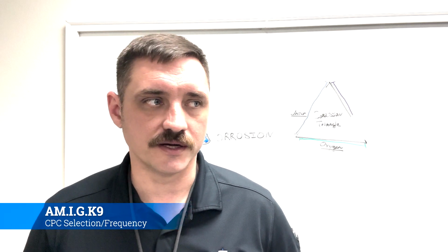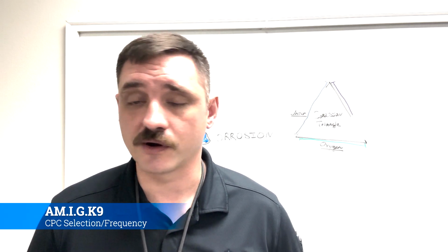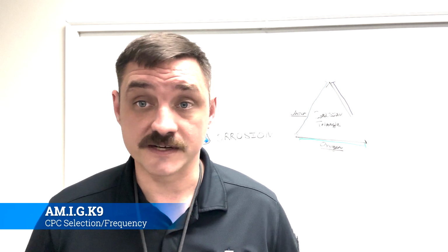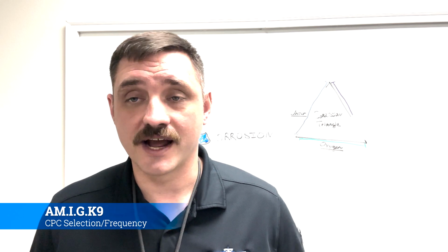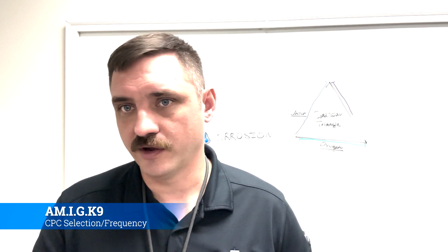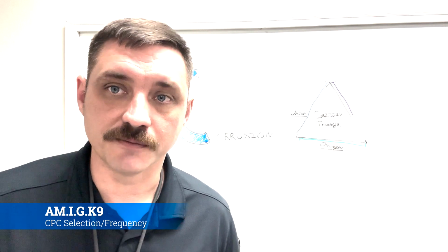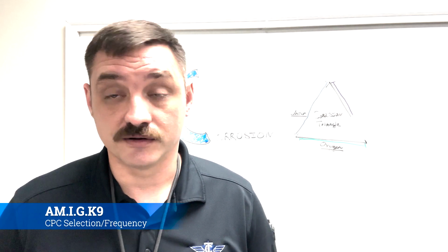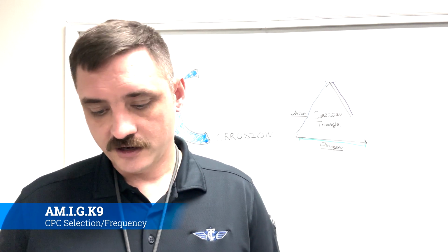A severe environment was basically a corrosion-severe environment. Whenever we were at Hunter Army Airfield in Savannah, Georgia, we were always flying within 10 nautical miles of salt water. It was considered a severe environment. So we were doing engine washes, we were doing preventative maintenance services every 10 days or every 10 hours, and so we were getting through these inspections a lot more frequently. But if you're the maintenance guy for, say, a private jet, maybe every 15 days, every 2 weeks, you're opening up the cowlings and looking in there to make sure there's no corrosion, we're good, and off you go.